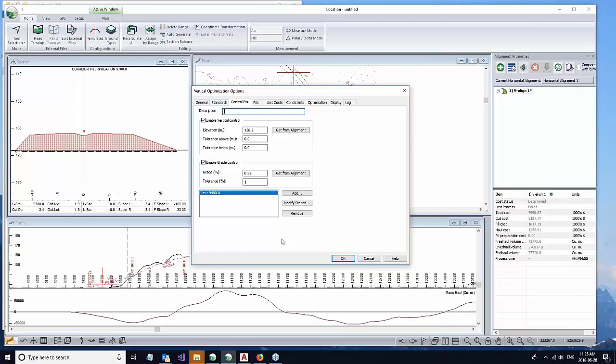And that's because the more you can constrain it, the less chance it has to move around. And you will eventually possibly over-constrain it or make it infeasible. So I generally recommend starting with something that's not constrained and progressively constrain it the way you want if that's what you want to do.